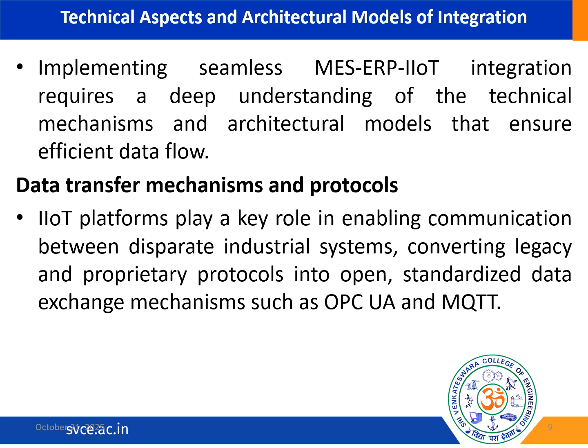So these protocols can all be considered. For the variety of interface standards in manufacturing, we can use protocols like Profibus, Profinet, Modbus, OPC UA, REST, ActiveMQ, SECS or GEM, Euromap 77. All these indicate different protocols that can be used by machines and systems.